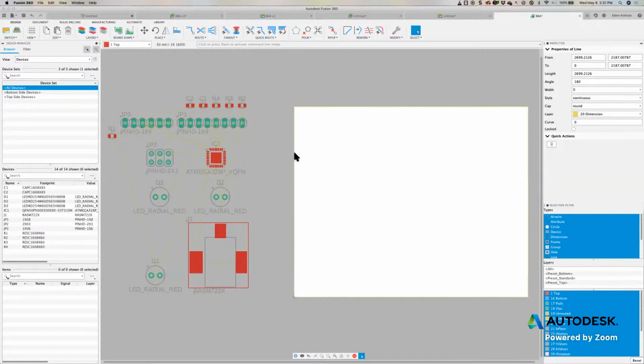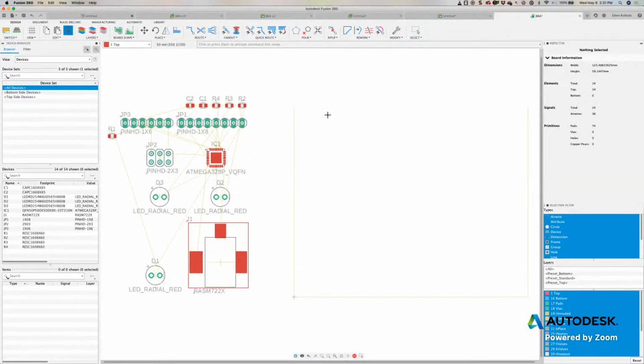If at any point you're working with Fusion 360 and you don't have this color difference, you need to stop what you're doing. If it's all white, don't continue working. It's very important that your board outline is an enclosed area. And this is true if you are Eagle users as well. If you're an Eagle user and you're going back and forth with Fusion 360 for your mechanical needs, it's very, very important that the board outline is actually an enclosed area.